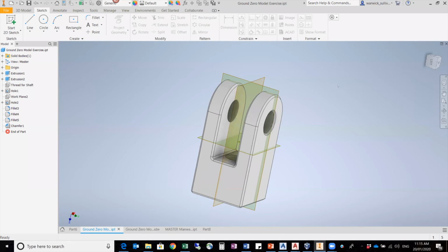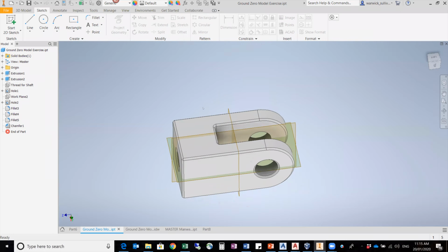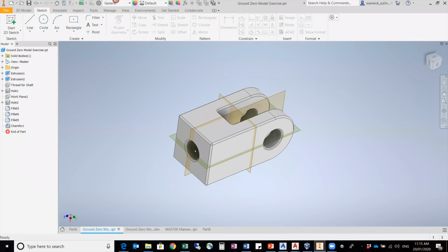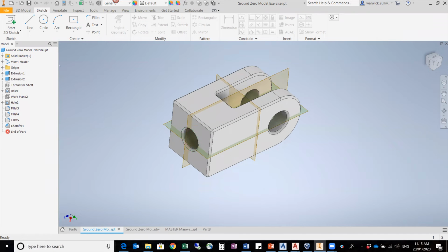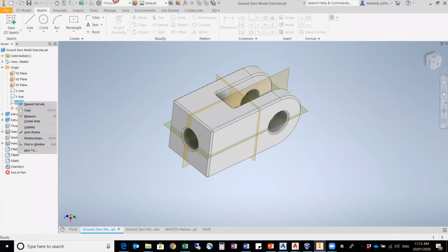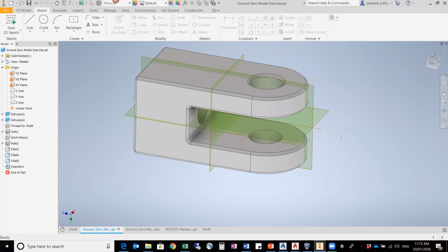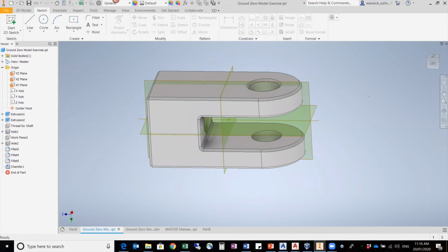And if it gets longer this way, no problem because you can extend it that way or that way without a problem. And you can use an axis through the middle here as well, no problem. So if I even go to my origin here, we've got the x-axis, y-axis, and the z-axis. If I turn that on, if you have a look, there's an automatic center line where the whole thing revolves around. See this? So that's another good reason to model everything from the center.